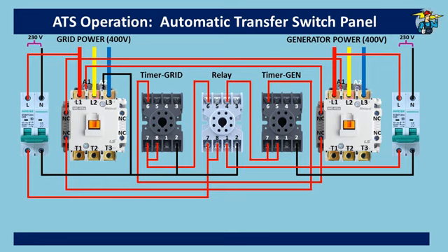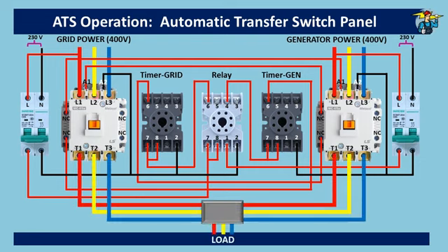Thereby, interlocking safety of contactors is provided, further to the safety provided by timer delay operation. The neutral wire is connected to the A2 of the generator contactor to complete the control circuit wiring. Power supply to the load is shown here now, and the control circuit power needs to be kept on by switching on the two breakers.